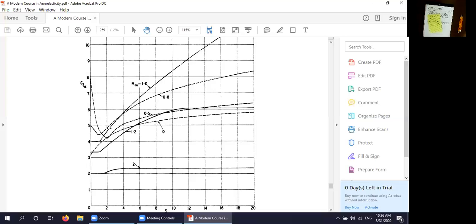And when the Mach number gets small, for example, the Mach number in our wind tunnel during a typical test is somewhere around 0.1, maybe 0.2 on a really good day. And so there's a temptation to say, well, it's so small, why not just set it to 0 and simplify the mathematics? Well, you can do that. You get this curve, but there's this little blip at time t equals 0. And the reason people were willing to accept that blip is because normally they were thinking of some finite frequency. And as long as the frequency is finite, you don't really have to worry about that singularity.